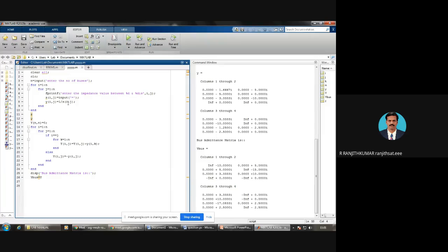And now I am going to apply the two rule here. For diagonal elements, it will add all the values, and for non-diagonal elements, it's just the negative sign of the admittances stored in that Y bus. For the diagonal only, we have another for loop, for k equal to 1 1, 2 2, 3 3, 4 4.